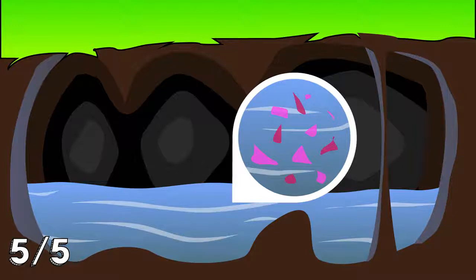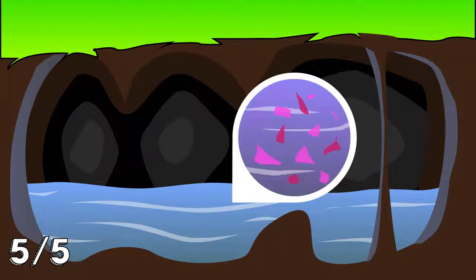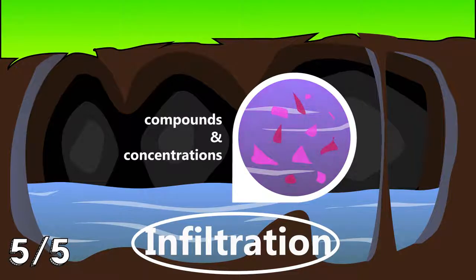Generally speaking, if the groundwater beneath the site is known to be contaminated, infiltration is not recommended. The movement of contaminants in groundwater can be accelerated by an infiltration practice, potentially resulting in environmental impacts to neighboring properties. However, there could be situations where infiltration practices can be implemented depending on the specific circumstances, including the compounds and concentrations present in the groundwater plume.